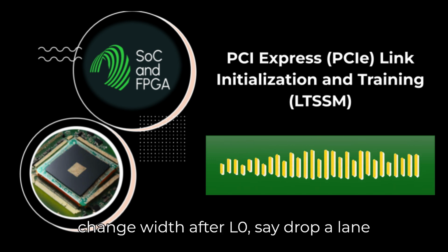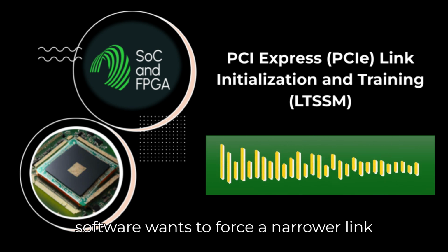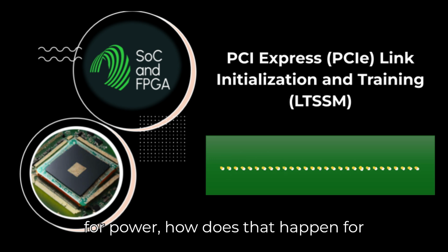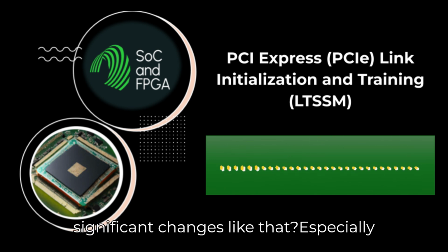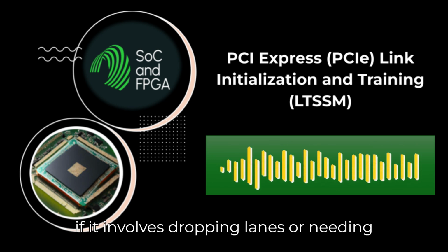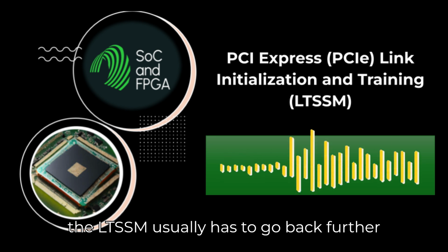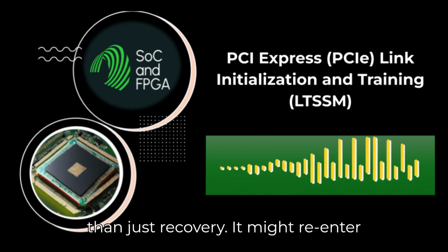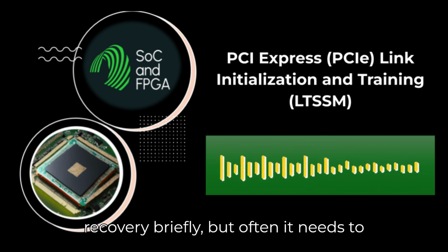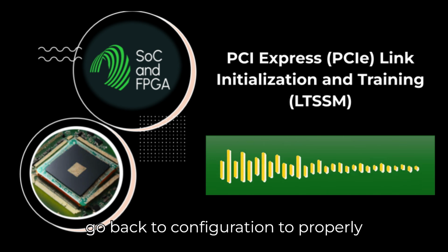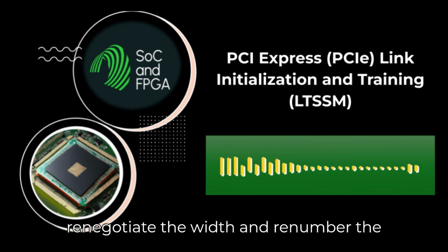So if you do need to change width after L0, say drop a lane that's become unreliable, or maybe software wants to force a narrower link for power, how does that happen? For significant changes like that, especially if it involves dropping lanes or needing to reevaluate which lanes are usable, the LTSSM usually has to go back further than just recovery. It might re-enter recovery briefly, but often it needs to go back to configuration to properly renegotiate the width and renumber the lanes.